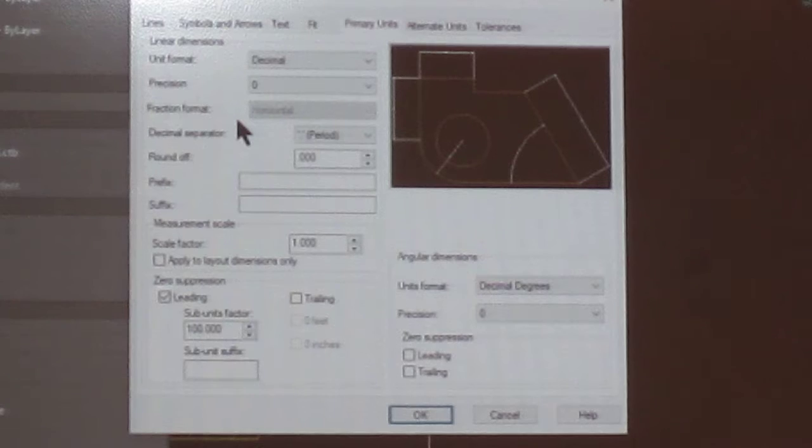Because I keep seeing this pop up on some drawings where I'll see dimensions and I see 0.50 or something for an English measurement. No, this should not be here. If I see metrics, and I'm seeing some metrics out there like 1.25, no, we don't have trailing. Your tolerance is plus or minus 1 millimeter. There are no decimal places. That's the base unit for metric. Metric is the millimeter. Why do you choose trailing for metric?